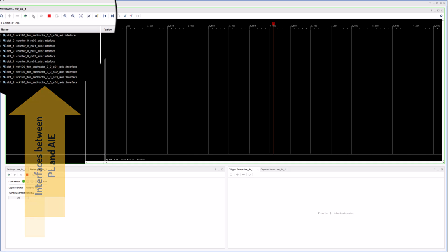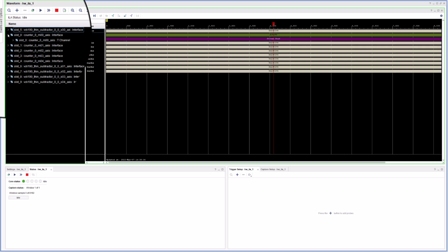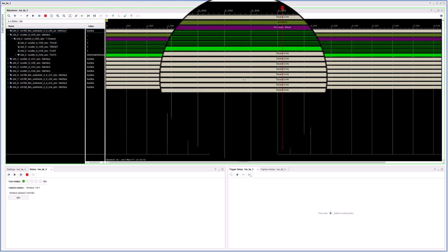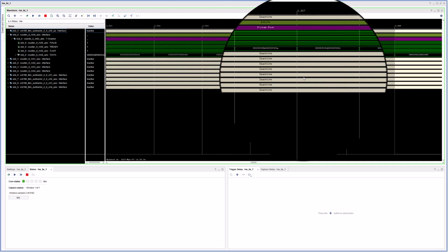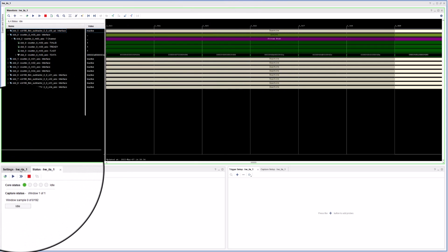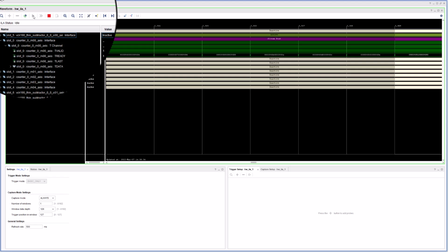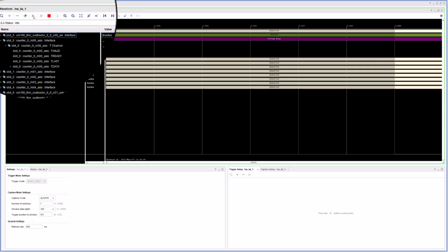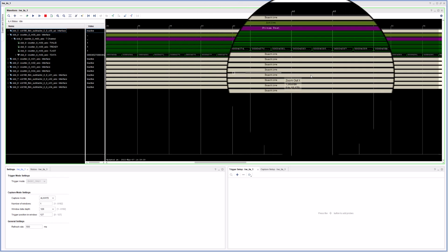The first impression here is that most of the sampled interfaces are inactive. The second observation is you must zoom in quite a bit to see data transitions. Decreasing the sample depth can speed up transfers and make the display more manageable. Casting a wide net is fine initially, but it's generally better to sample less and be more selective on where you look.